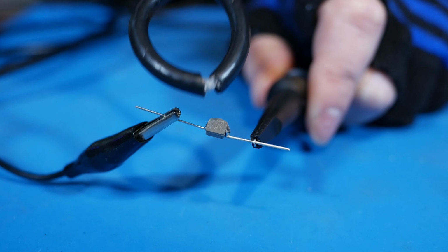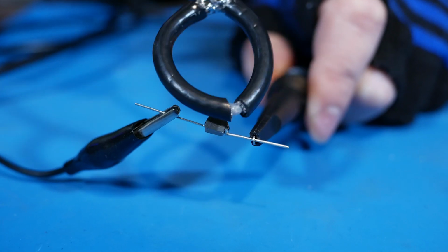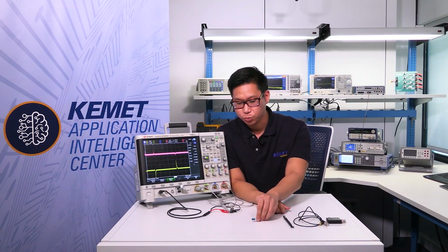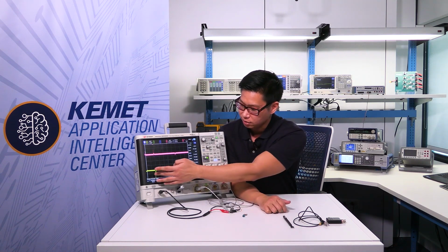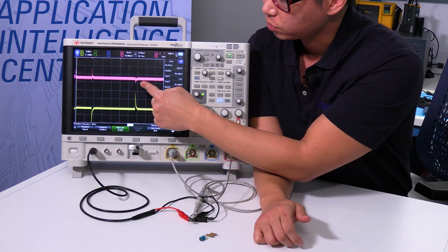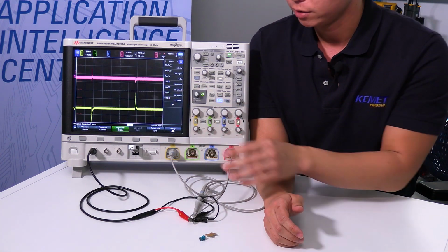So yeah, we can see that there's much less noise coming off of the metal composite shielded inductor than the ferrite core one. And it's worth noting that, at least in my setup, I'm comparing two 33 microhenry inductors. So they're exactly the same value, and you can see that the signal going into it is exactly the same, but the response I get from the electromagnetic interference coming out of it is much smaller on the MPX or the metal composite inductor.